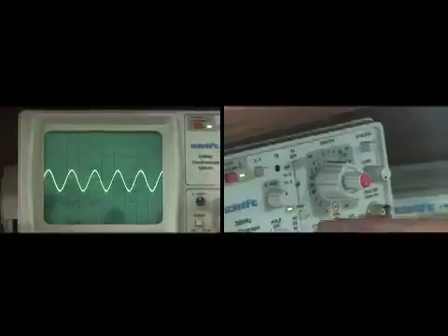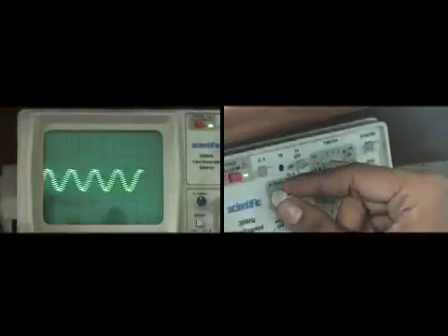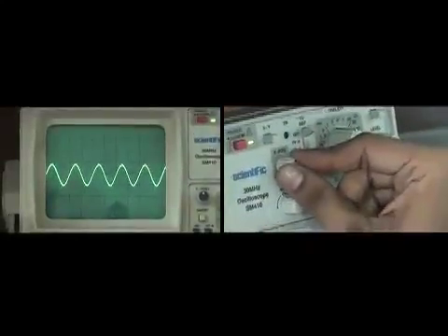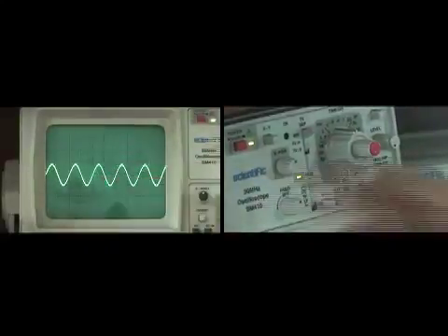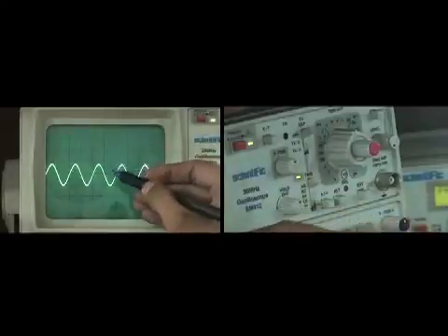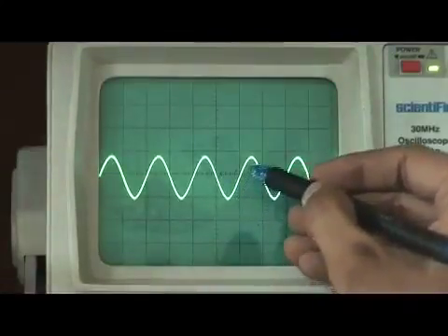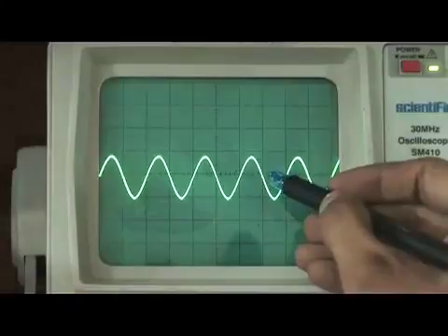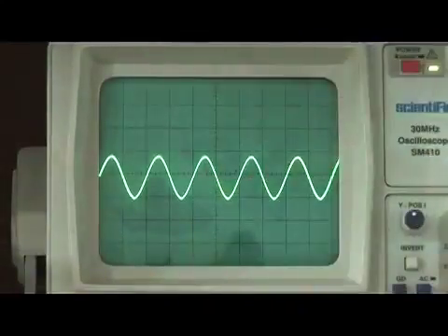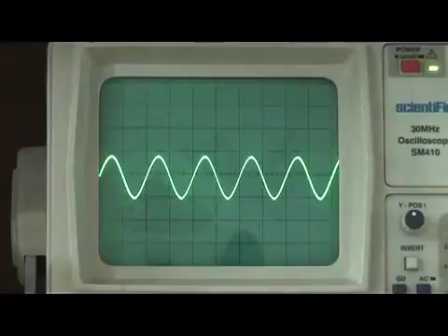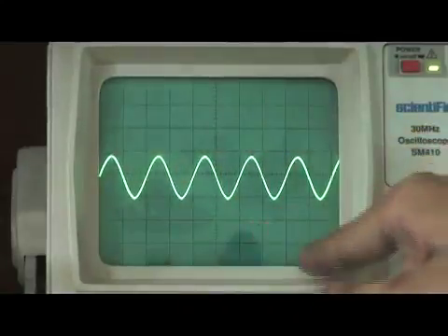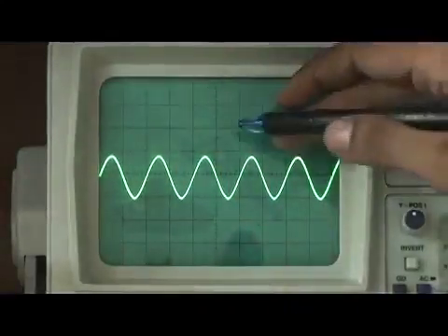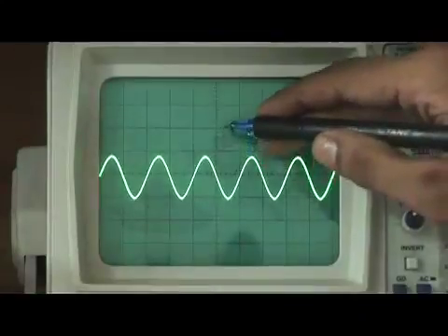Using this X position knob I can move in the X direction. I set it in a proper place where I can take a reference point here and say that this is going to be 1. From here it goes this way, and till here it completes one cycle. So from here I can easily count the number of blocks. You might be confused about what the number of blocks is. You can see this entire screen is divided into small blocks, various squares. Again, you can see that each square is divided into various subdivisions.